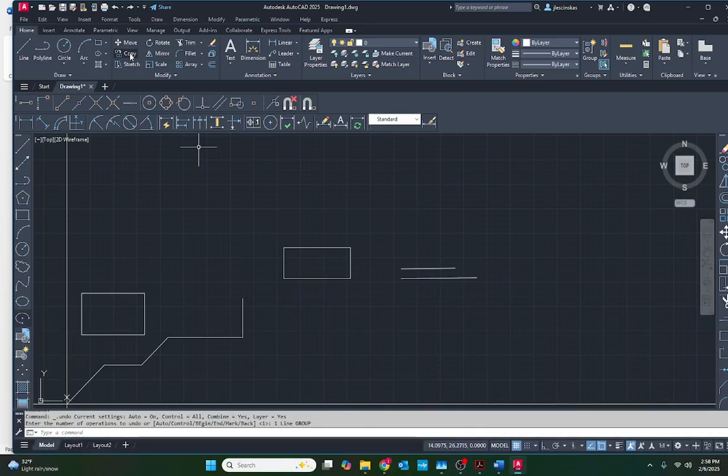So we had those grip edits when we were doing that copy. Then we did a line, drop geometry. I'm not sure exactly what that is, but this is the whole list of how far we can go back, in our zooms as well. So just be careful though. If we come to this undo, you're going to undo your whole line. You really want to type Control Z or just type U, enter, to do an undelete.